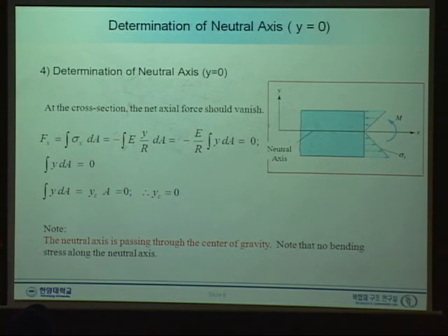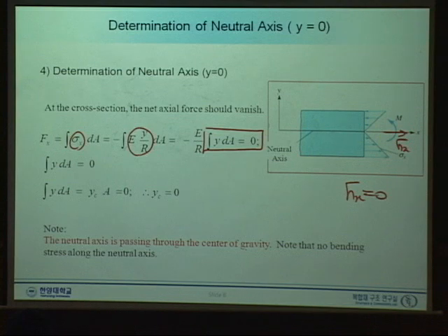Yes, simply there was no external force Fx, and using this condition Fx equal to 0, that's how we determine the neutral axis. So sigma x, we already derived, which is this one, and E and R are constant. So simply we have integration y dA should be 0.